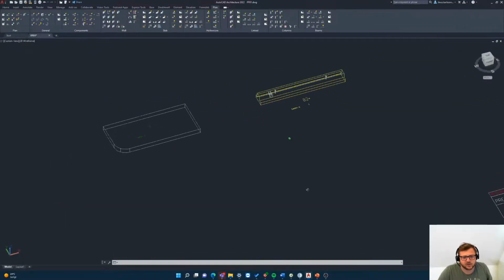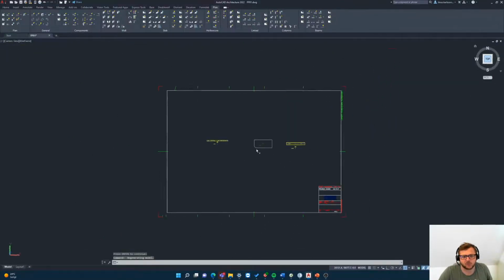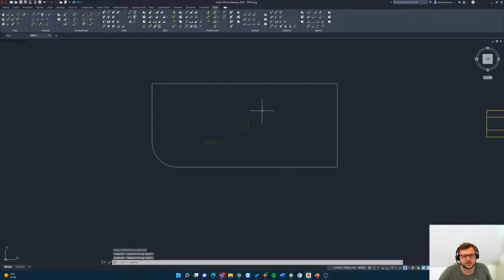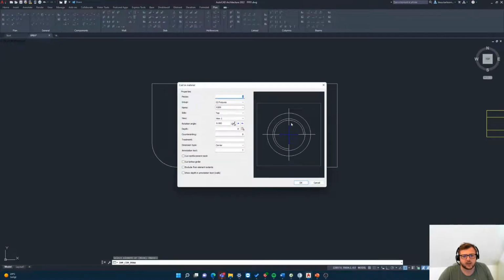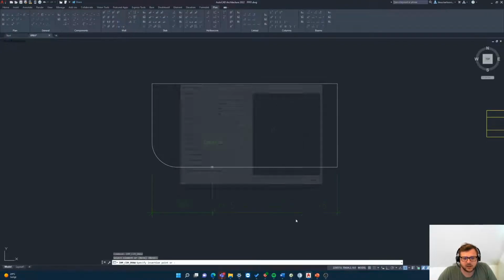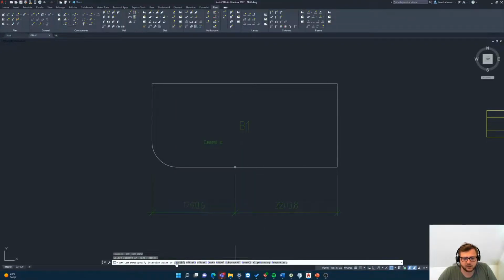The last feature I want to show you today, or part of the feature, is for slabs. So here we have a balcony, and maybe you want some custom material to secure the railing. It should have a standardized distance from the edge of the element. So to do that easily, we can start the same command. Select, in this case, a bracing here, top side, and say OK. So here you recognize these options, but you also have this align boundary. So we can just select it on one of the boundaries.